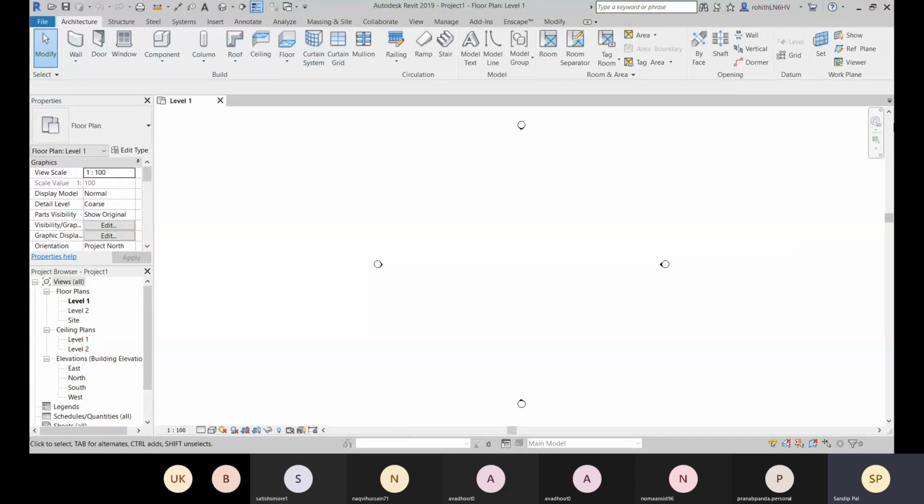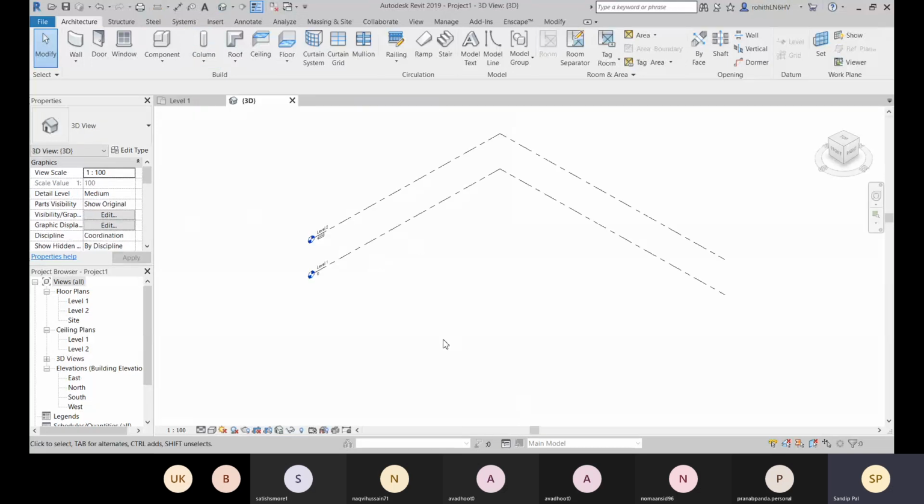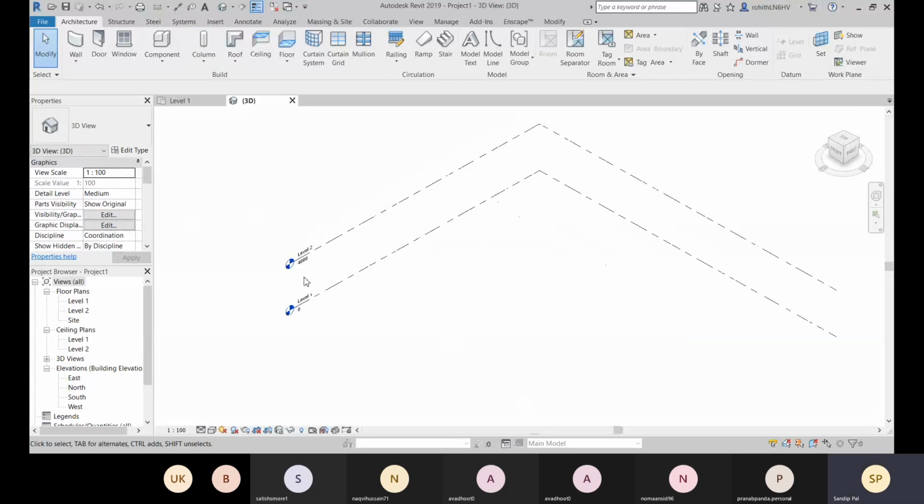So the overview and the UI layout we have already learned about, and about this elevation, what are these calls? These are your elevation cameras. So from this we are getting these elevation views. Okay, and we also have one 3D view, and we have two default levels created. So these two default levels are already there, and these two levels will represent two different heights.